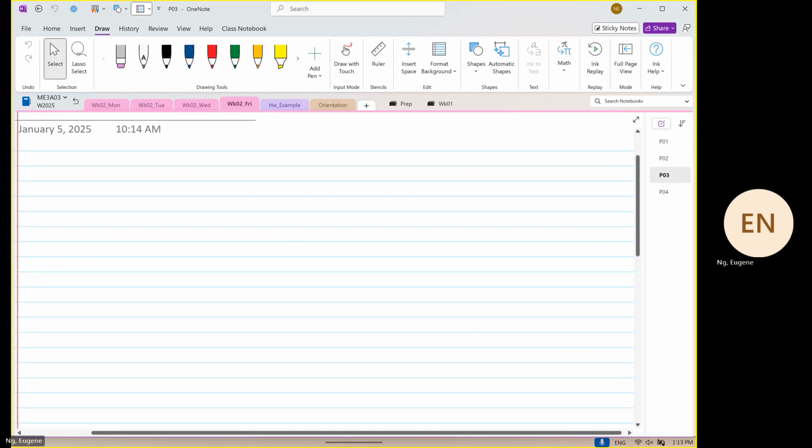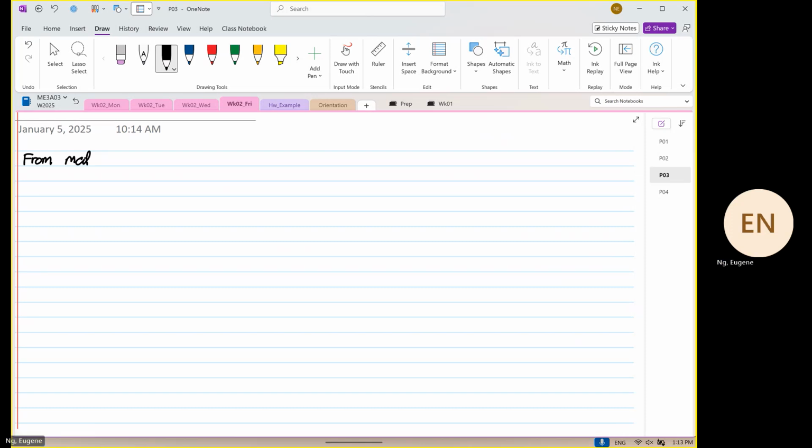From the materials handbook, for L2 steel, the Young's modulus is equal to 200 times 10 to the power 9 Pascal, and the yield stress is equal to 703 times 10 to the power 6 Pascal.